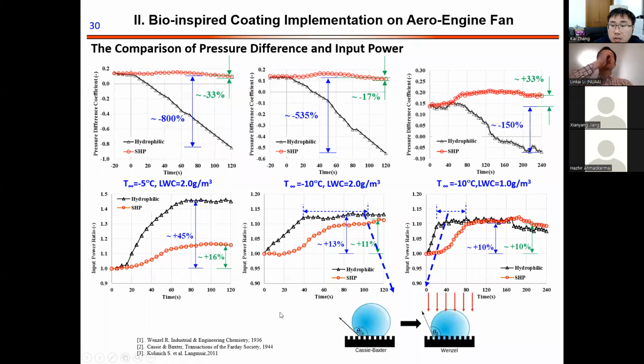Essentially, I remember Rai did a test in the icing tunnel with different wind speeds, and Rai thinks it is droplets impinging on the tiny structures of the surface, where the velocity is high, so the dynamic pressure is very high. Instead of flowing on the tiny structures, the pressure will push the droplets into the micro-sized structures and make it lose super hydrophobicity.